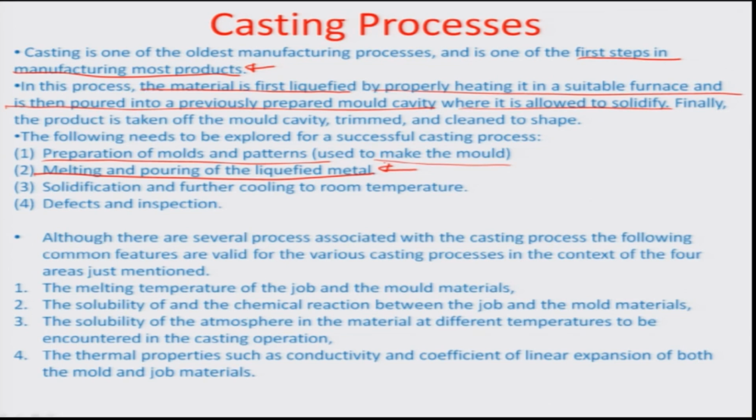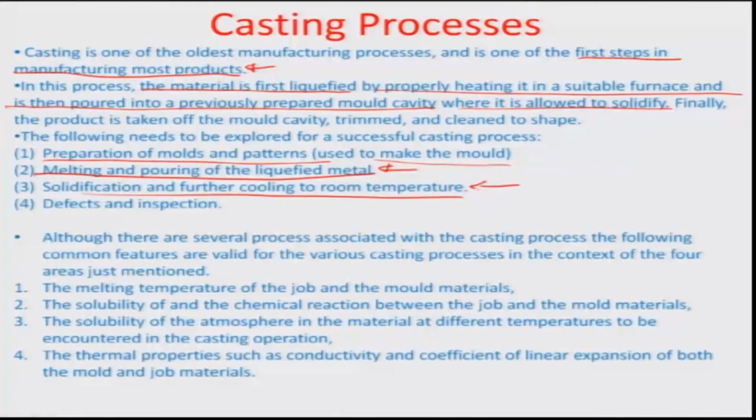And so during all this process, there is always heat transfer, because remember, the mold is always at a lower temperature than the super hot liquid metal which is flowing through it, and therefore there is always a possibility of solidification before entering. And so the processes should be designed in a manner so that the liquid metal really enters before the solidification happens. And then you have to give heat to finally the solidification and further cooling to room temperature.